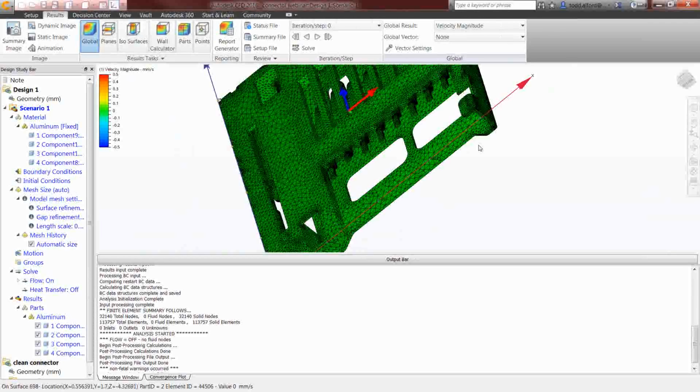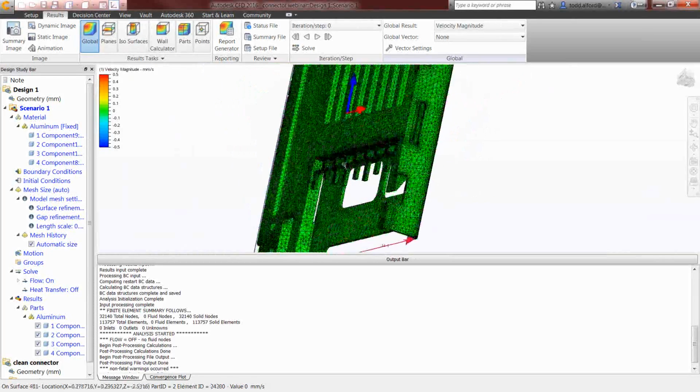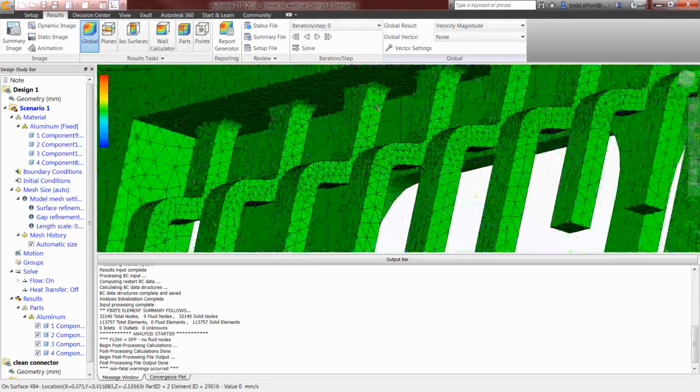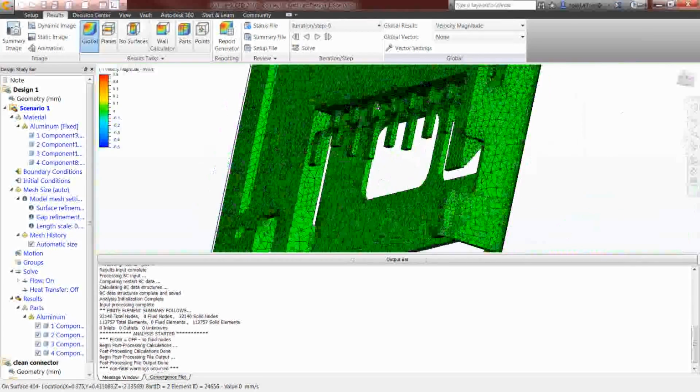In this case, what I have found is that small edges, sliver surfaces, part slivers and model slivers typically will still mesh. It's just going to cause an unnecessary concentration of mesh elements, typically where the model assessment toolkit is pointing those things out.